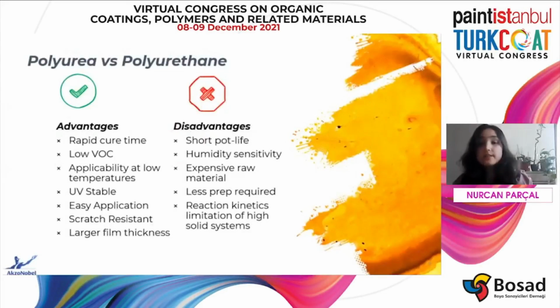However, there are significant disadvantages of polyurea coatings. For instance, polyurea coatings have short pot life and high humidity sensitivity. Due to rapid reaction time, reaction kinetics limits high solid systems by decreasing mobility. Also, polyurea raw materials are more expensive.